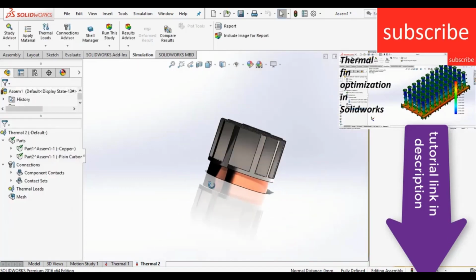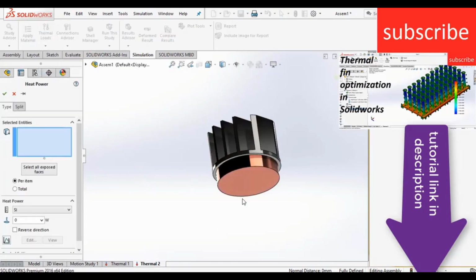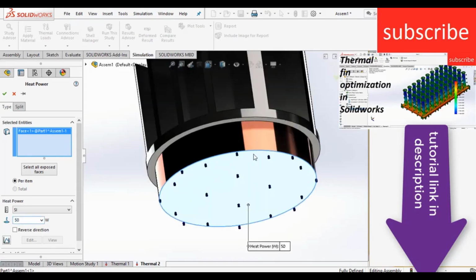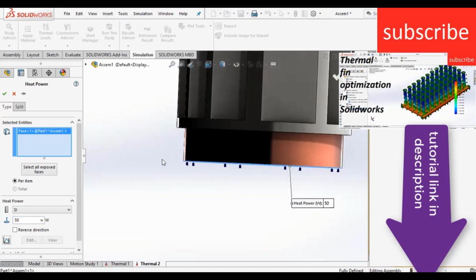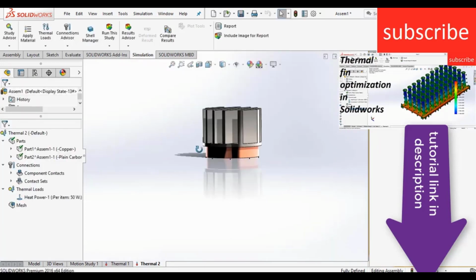Click OK. Now go to the thermal loads, click on heat power, select the bottom face, enter the value of heat that you think is going to enter the chip. For example, I am assuming that during simulation my chip is getting 50 watt power, so I am giving a value of 50 watt.